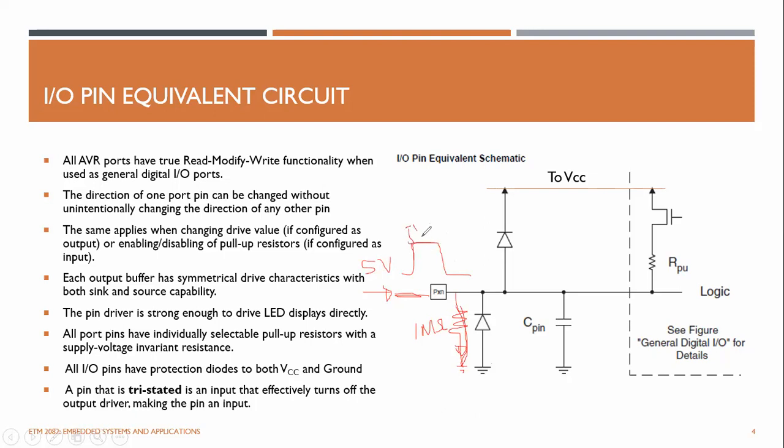If it is 5, it will be 5. And if you have low impedance, like let's say 100 ohms or something, definitely this 5 volt will be dropped to like 3 volt or something. It is not desirable, right? So keeping high impedance is very critical when you connect sensors to these input channels.